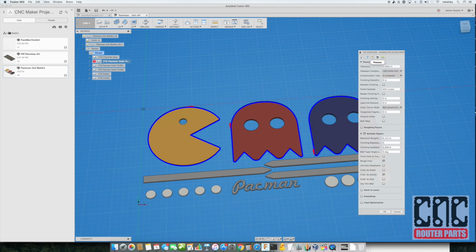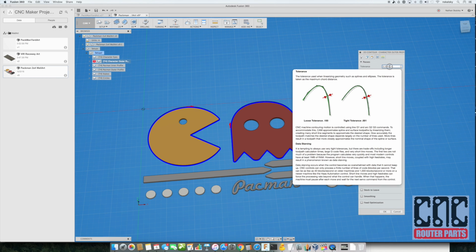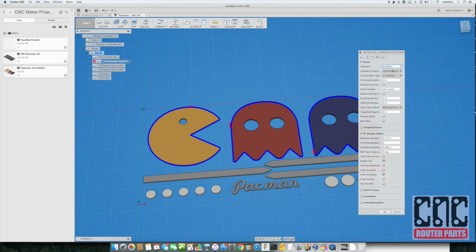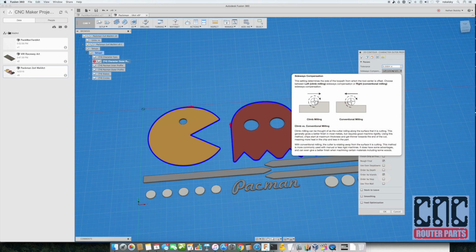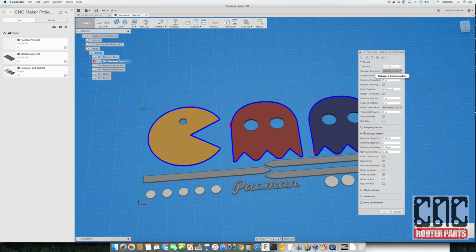Switching to the Passes tab, we can see the tolerance setting. And just a quick word about these defaults. You'll create outstanding G-code from Fusion as long as you remember to manage your feeds and speeds on the first tab and the tolerance and smoothing settings on this tab. Always ensure that these settings are not left at default values, which are often optimized for steel machining in traditional low IPM CNC mills. Let's change the tolerance to match our machine, in this case 0.001 or 1/1000th of an